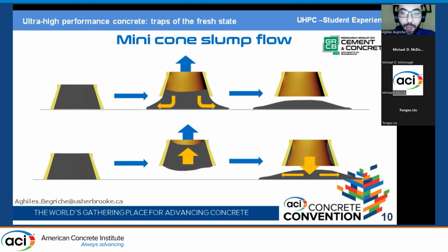So for UHPC concretes, if you take more than, let's say, around 1 minute approximately, it depends on the quantity of water, the superficial tension between the internal cone surface and the studied material increases fast, given the low water content in the material, even if you correctly wet the cone.